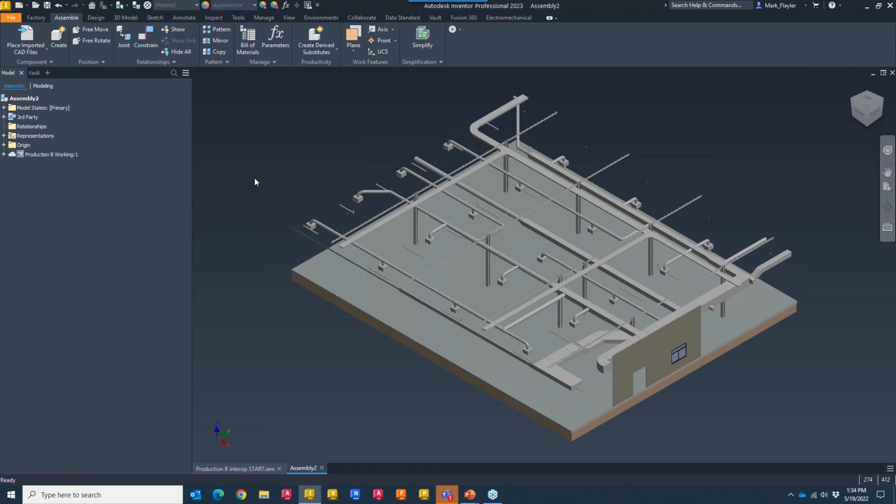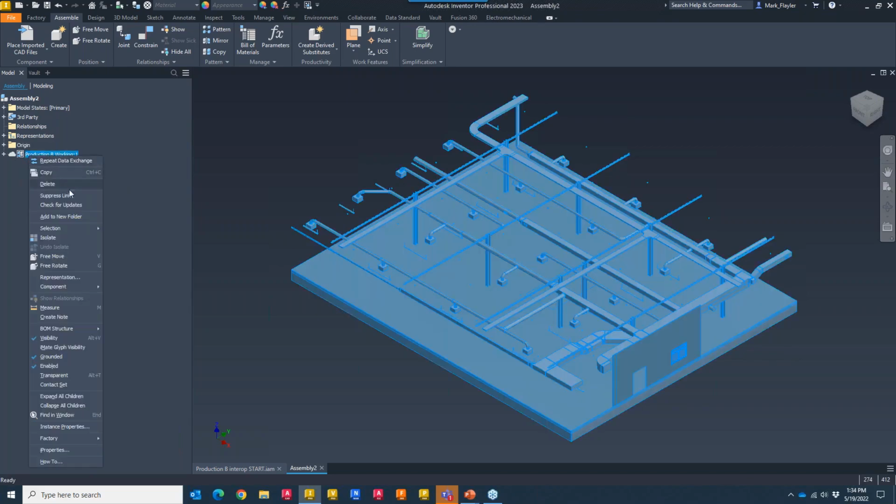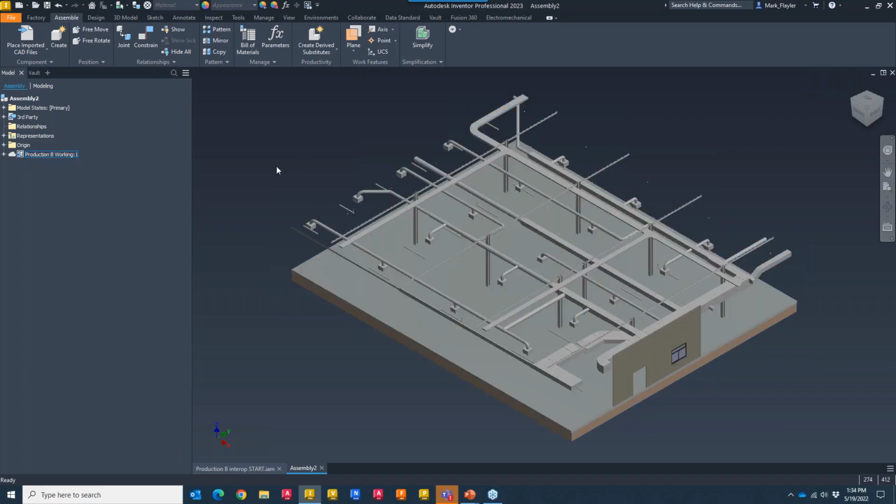And what's interesting about this is when it's brought in, it kind of looks the same as the AnyCAD reference. It's got that little cloud icon there. I can come in here and check for updates, but I can't break the link. I can just check for updates. And this actually behaves like it's Inventor components. I actually have individual parts that I can click on and turn visibilities off. Okay. So that's actually kind of neat.